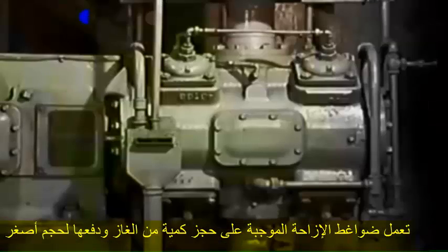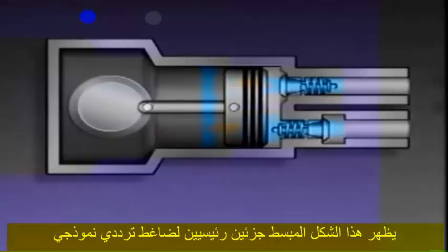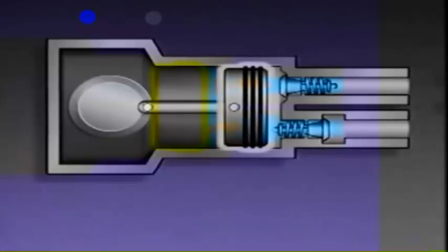Compressors. Positive displacement compressors work by trapping a certain amount of gas and forcing it into a smaller volume. A common type of positive displacement compressor is a reciprocating compressor. This simplified illustration shows two main parts of a typical reciprocating compressor: a cylinder and a piston.